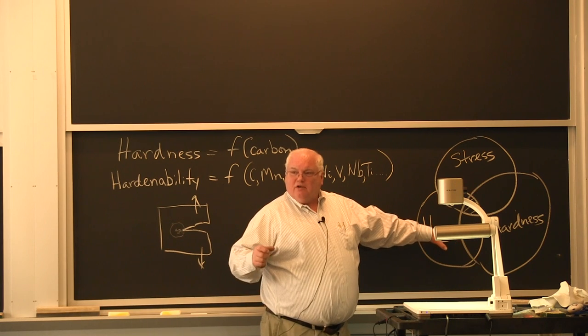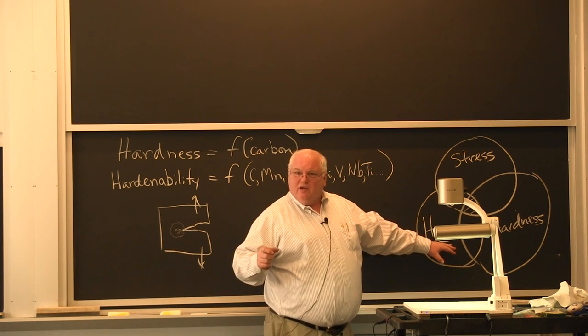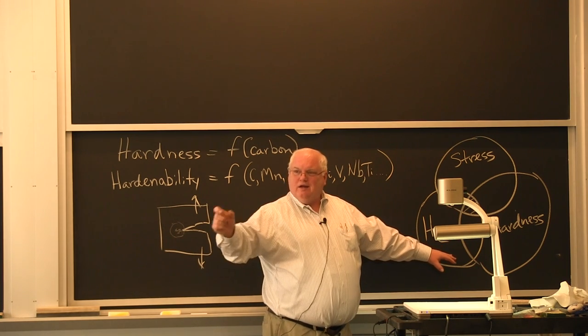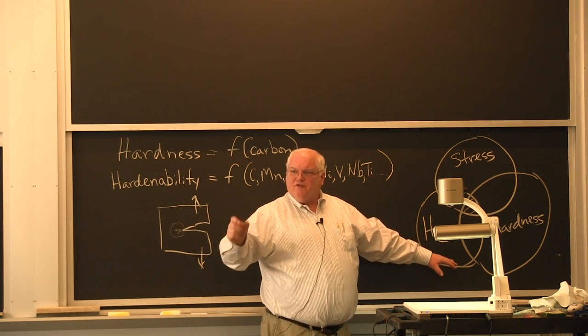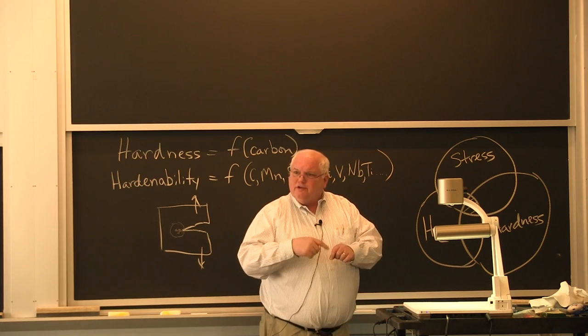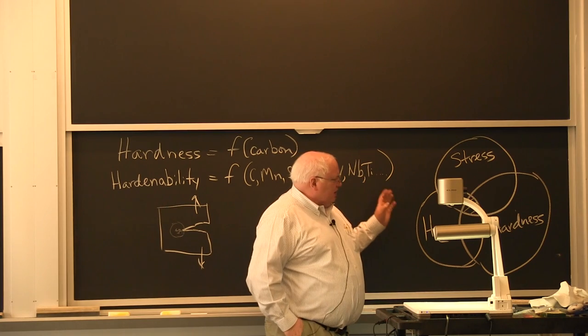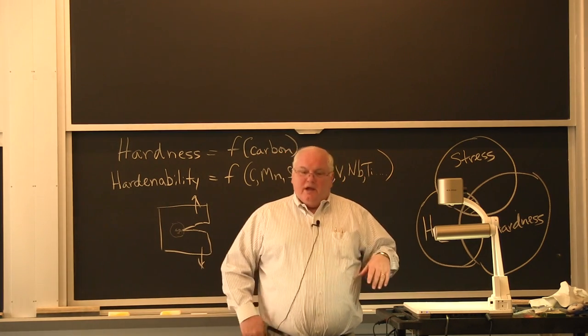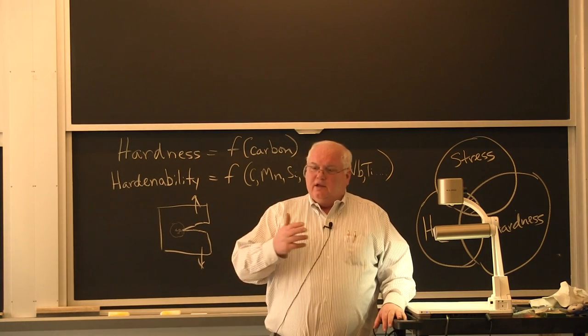They didn't check them out back in 1955, where you could only have them out of the oven for 2 hours, and you had to bring back a stub for every electrode you got. Some little clerk there was counting your stubs before you could get more electrodes. They didn't have all these hydrogen controls,